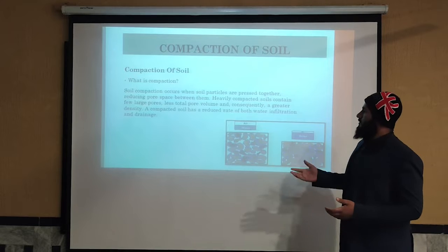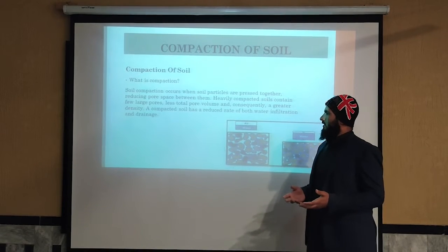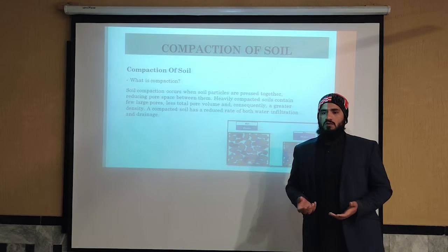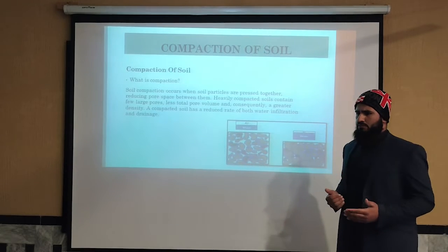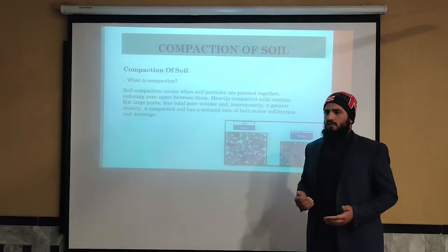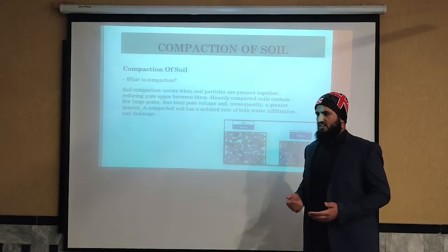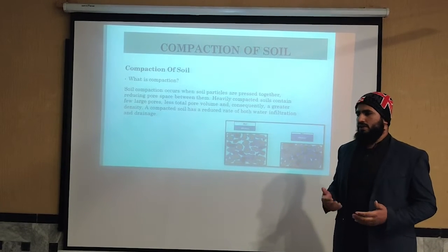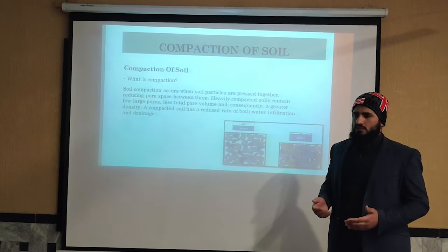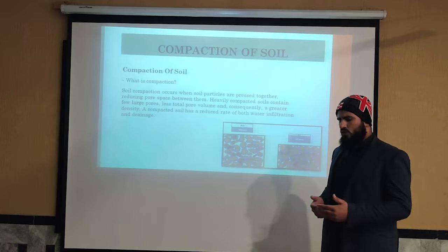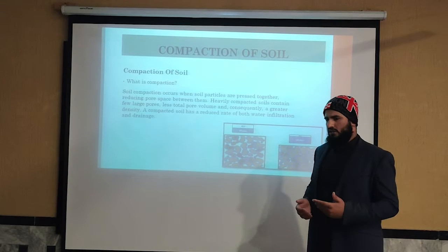Compaction. What is compaction? Soil compaction is a process of densification of soil by any force, whether a steady force or a dynamic force. We use different equipment for this purpose. So how can we compact the soil, and why is it important? Densification of soil is very important because it removes air voids and moisture content.